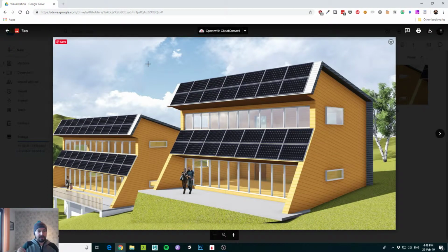That's because this is the optimal angle for the winter time. During the winter you need the most electricity for actually heating the house, and the optimal angle for where we'll be building in Bulgaria is 60 degrees. So in the winter, that position and orientation of the solar panels will produce the most electricity, from roughly November to February.